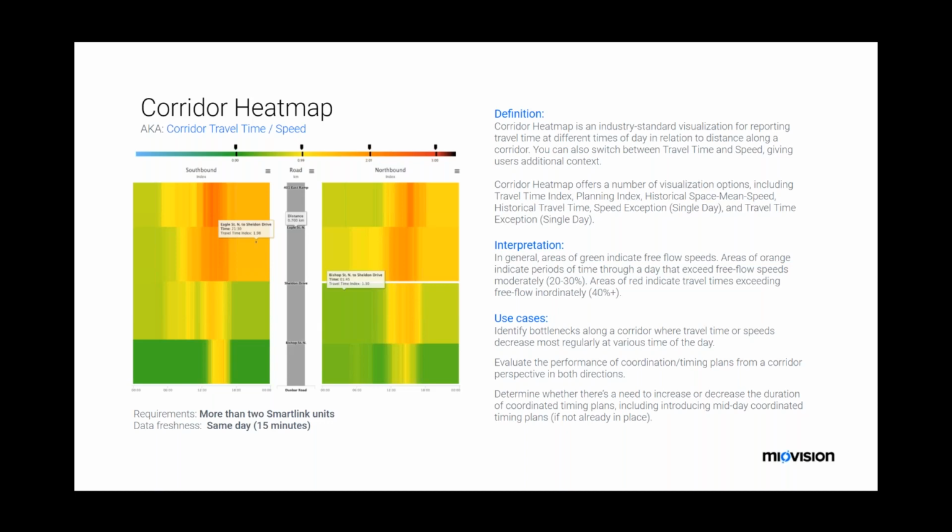And what it's showing you is basically top to bottom is southbound and bottom to top is northbound, and then each band is representing the relative distance between each intersection. But when you compile that across the entire day, across an entire corridor, you actually get basically a scan that shows you where in the network it is slowing down. And so when we look at where it could be slowing down, it can point to where the problems may be.